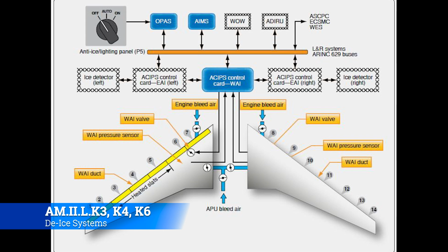There's also an interesting stat that the majority of all aircraft fires are caused by anti-ice systems. The reason is that you're piping super hot air into these confined spaces, so if there's anything up there that can catch on fire, it probably will, because you're going to be above the flash point of a lot of different substances that we work with on a regular basis. So if there's any sort of FOD problem, or degradation from being used over a long period of time, or damage, you could end up having a serious issue if you start dumping bleed air into some space it's not supposed to be. So just know that ASIPs is going to come back whenever we get to the 3.7 Gen Fam on anti-ice.